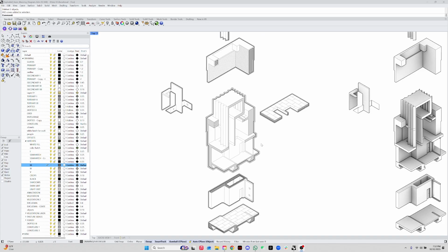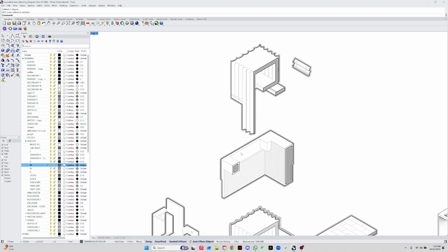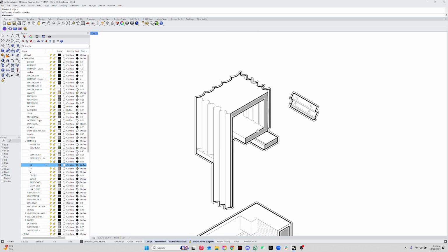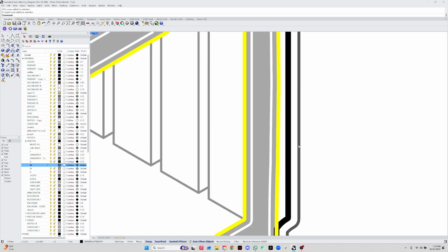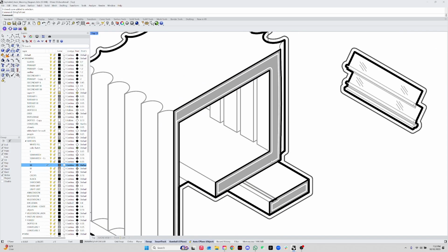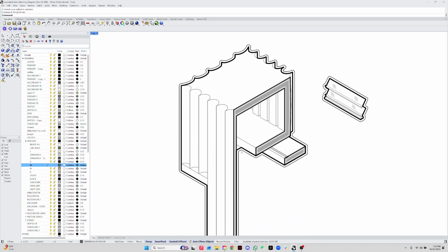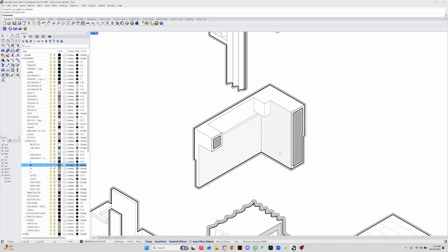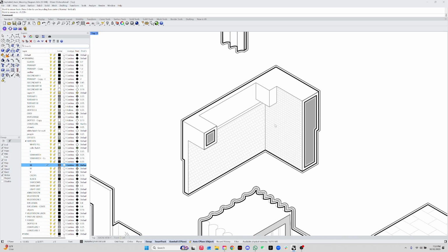Okay, so now that I'm done with adding all the details, I actually went in and added a border using curve boolean. Obviously, if you see stuff like this, just always bring your line to front. If you see anything going over the line that you don't want, just do bring to front, so then everything is nicely clean. So I went in and I added different hatches. I started to break the walls differently in each of these studies.